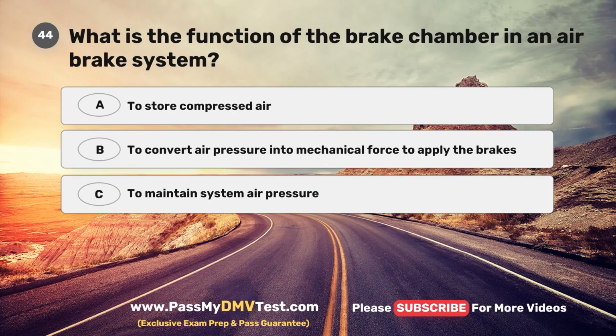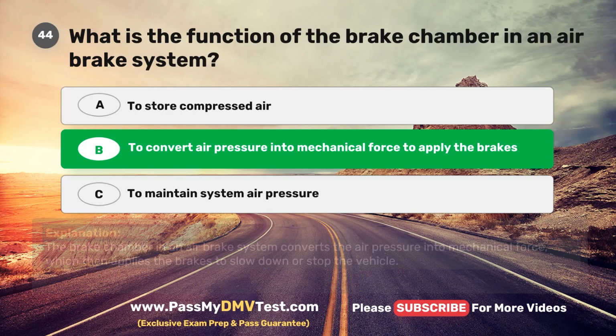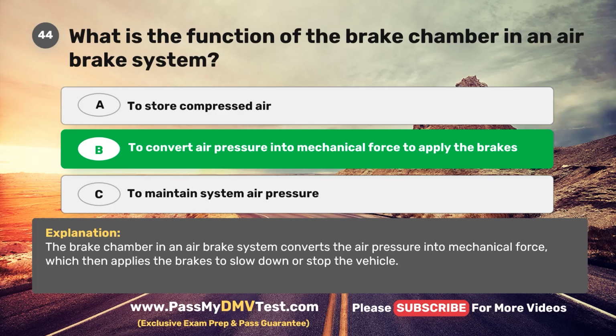Question 44. What is the function of the brake chamber in an air brake system? A. To store compressed air. B. To convert air pressure into mechanical force to apply the brakes. C. To maintain system air pressure. The correct answer is B. To convert air pressure into mechanical force to apply the brakes. The brake chamber in an air brake system converts the air pressure into mechanical force, which then applies the brakes to slow down or stop the vehicle.